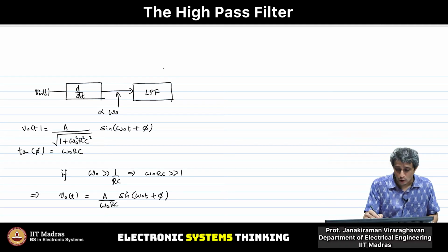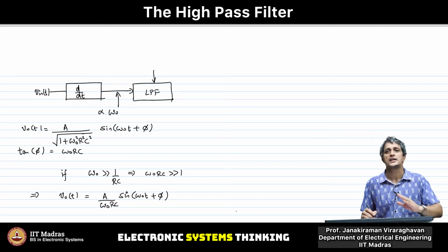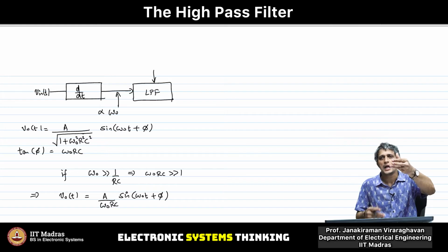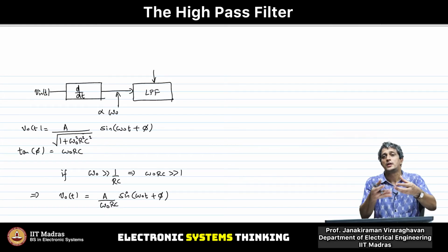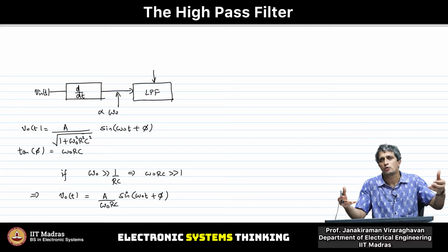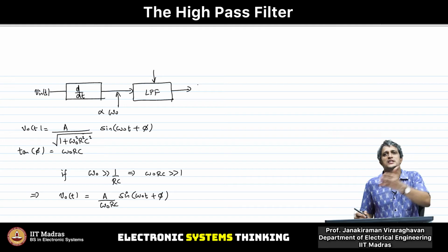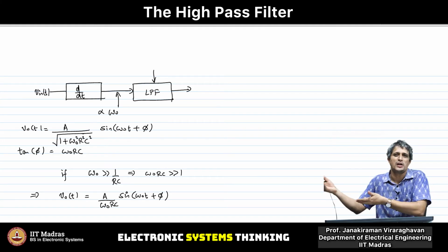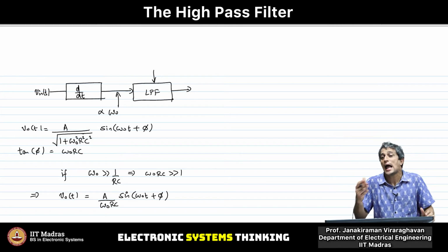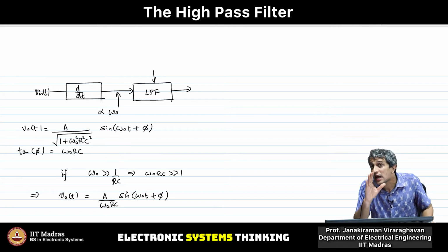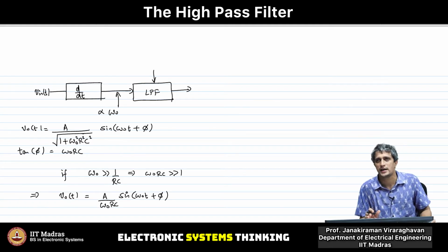Therefore, if you consider the effect, the input has got scaled by omega naught and the low pass filter is now trying to divide by omega naught, and therefore the two omega naughts will cancel out each other, and effectively the output will just be A sine omega naught t plus phi or A cos omega naught t, it does not matter, right? The amplitude will remain unchanged, and that is the key point that I want to highlight here.